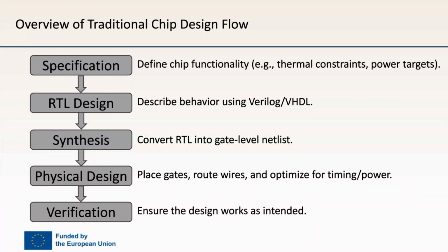Next is the RTL design, where the chip's behavior is described at an abstract level using a hardware description language like Verilog. This bridges the logical functionality of the chip with its physical implementation. The synthesis phase follows, where the RTL description is transformed into a gate-level netlist, serving as the blueprint of the chip at the logical gate level.